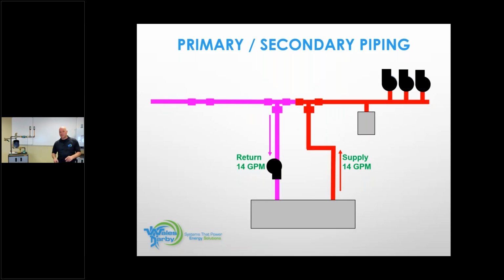So just ask this question. This is your home. You're paying for the BTUs that are being supported by this boiler. It's cold outside. All 3 circulators are on. Boiler circulator is on. Boiler is running full speed. This is your house. You're paying for the heat. What do you want going on between those 2 T's right now when all 3 circulators are on? And I am not giving you a flow rate out here. So you just tell me what you want going on between those T's when the whole house is up and running.